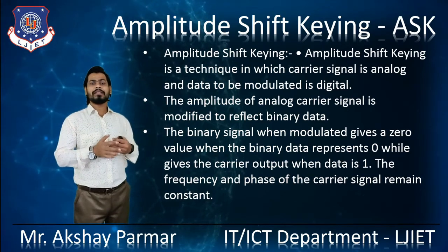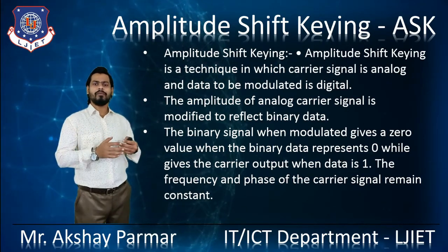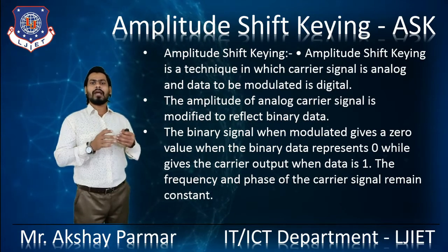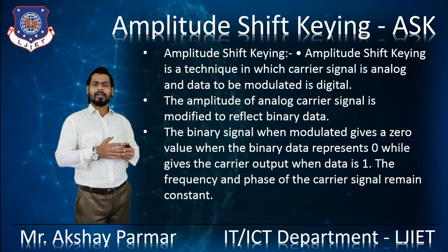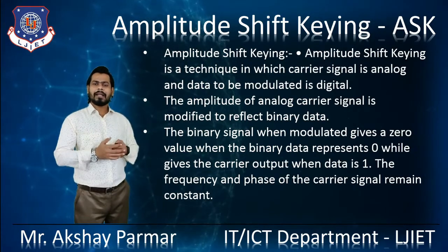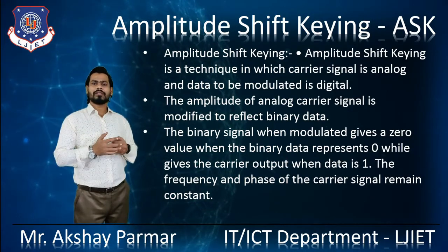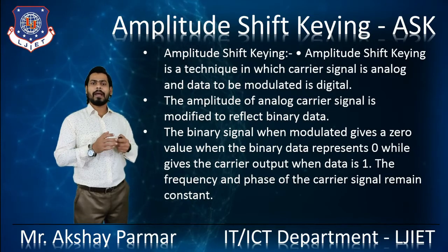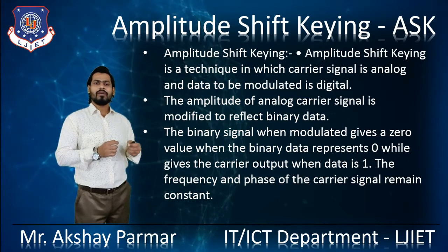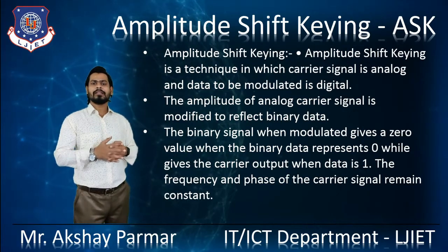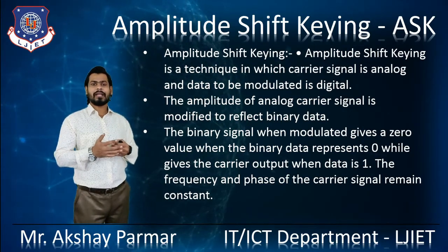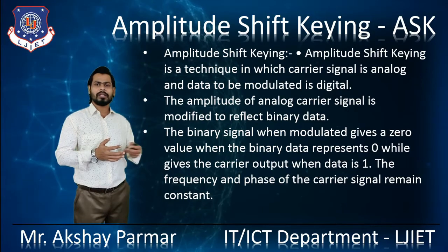The digital data is in the form of binary data. When modulated, it gives a 0 value when the binary data represents 0, and it gives the carrier output when the data is 1. The frequency and phase of the carrier signal remain constant here.